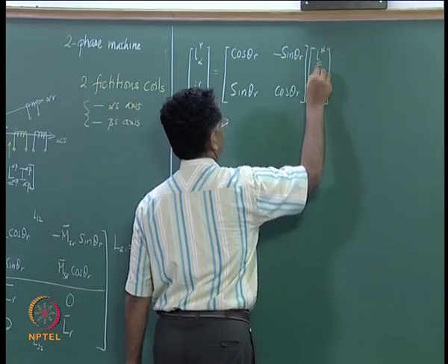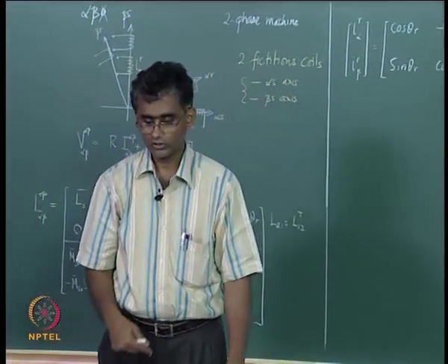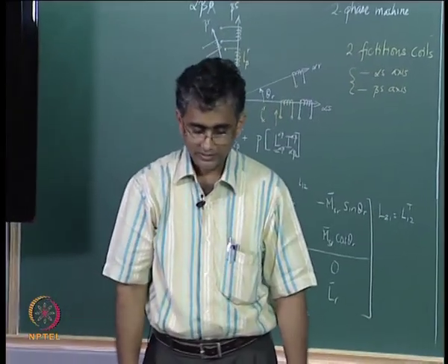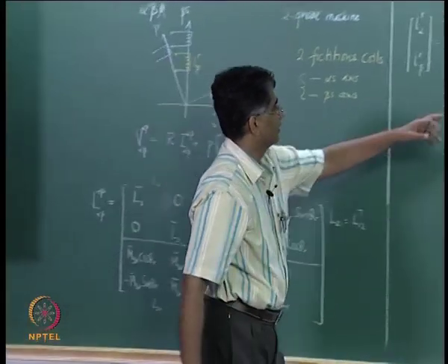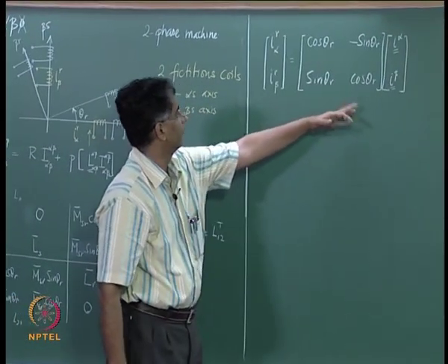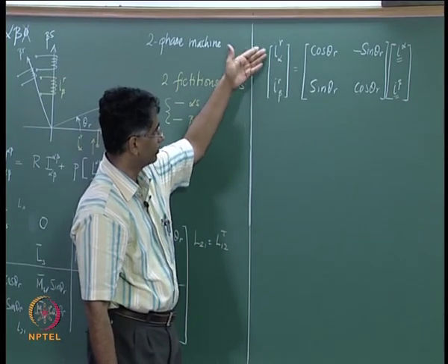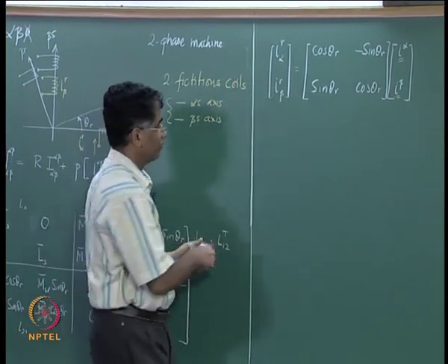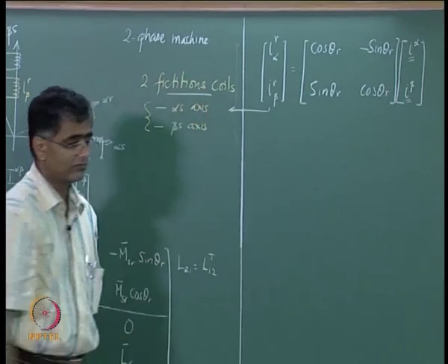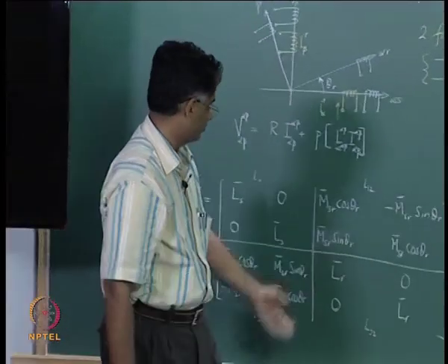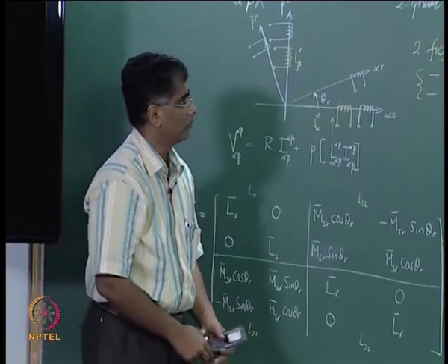So these are the currents that are actually flowing in the rotor, of course in the 2 phase axis of the rotor, not the 3 phase machine, and these can then be equivalently thought of as some currents, the same MMF being produced due to these 2 currents which are flowing now. These currents are flowing in the pseudo-stationary fictitious alpha s winding and the beta s winding.